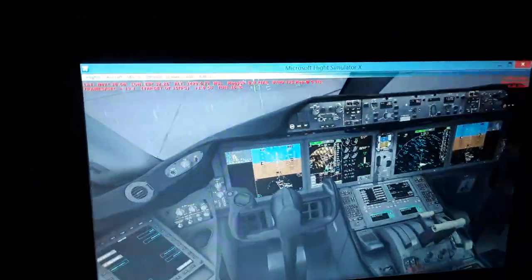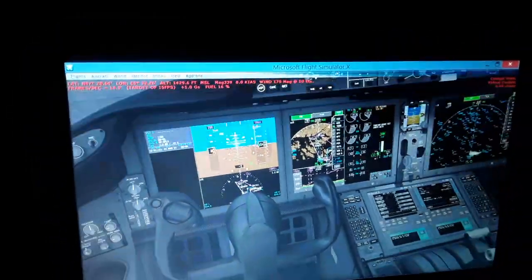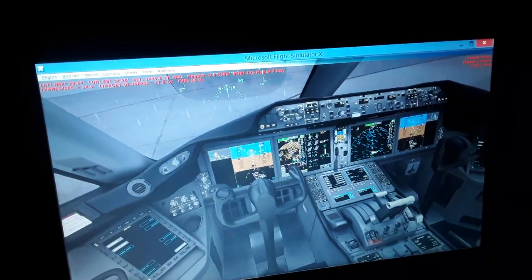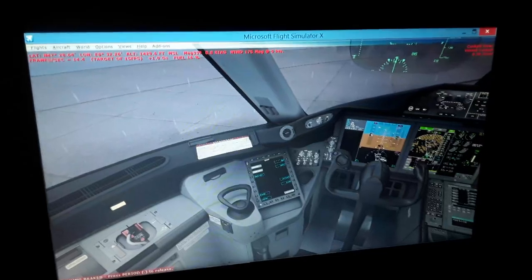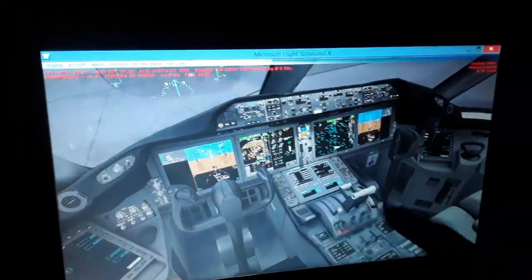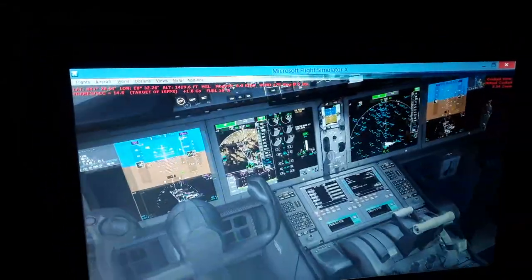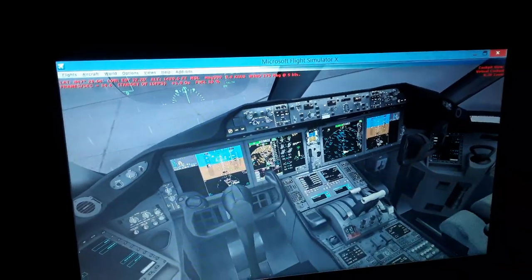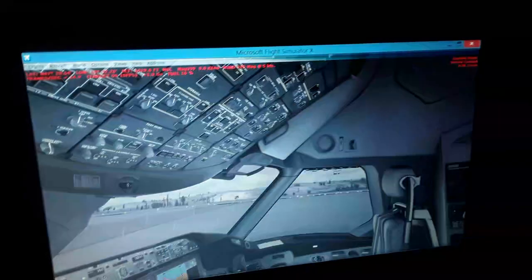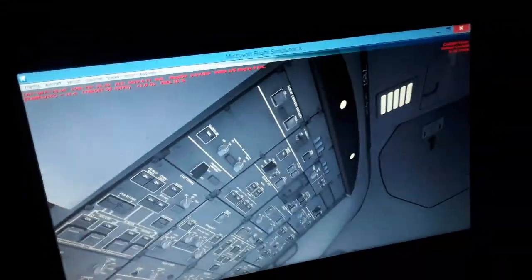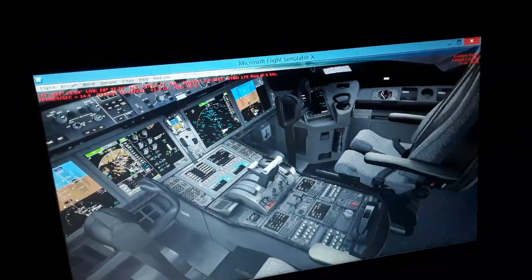The inertial reference, the alignment of the aircraft with respect to the magnetic North Pole and the geographic North Pole and its GPS location. So it makes a lot of calculations, laser gyroscopic acceleration, deceleration, air data. So it's a very important instrument over here, air data computer and inertial reference system, the alignment. So I'm gonna show you also how I created the flight plan.